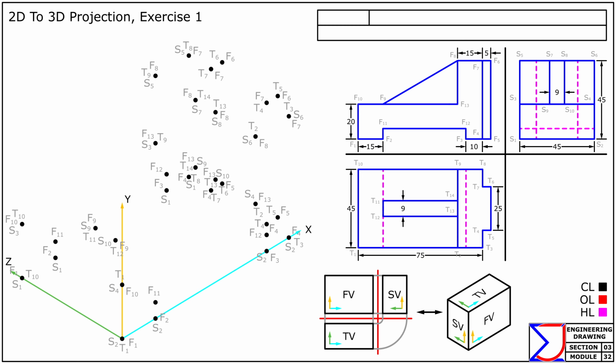So, all points from the side view have been successfully placed. Now that all points are correctly placed, refer back to the orthographic views and begin connecting them in isometric space to form the complete 3D object.